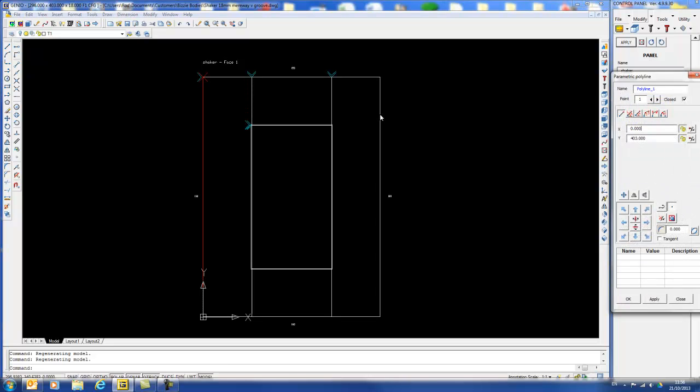So if I click on the outside polyline, and where my red cross is, which is the top left in this case, that is the point that we're looking at. So on this we're looking at the top left, and I want it to be linked to the top left, so I click the top left of this box. That position is always at x0 and it's always at dy because it's the furthest point. I move on to the next one.